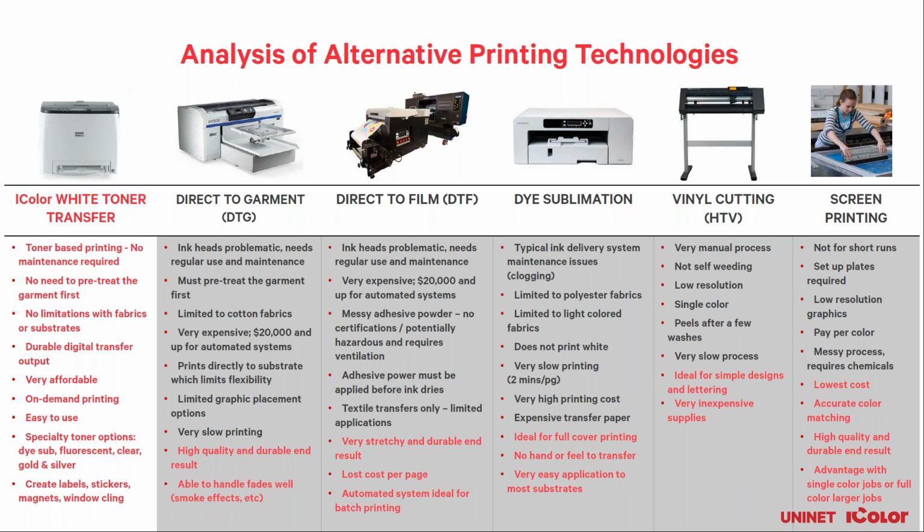Instead of an A to B marry that we all might be familiar with white toner, where you print on a transfer sheet and marry to an adhesive sheet, in the case of DTF, you are taking your printed sheet while it's still wet with ink within the first 10 or 15 minutes of being printed, and you're either manually dipping it into powder and then curing it for 2 minutes in a heat station, or it's going through an automated system where the powder is applied, vibrated off, and then heated all at once. So there's an adhesive one way or the other.